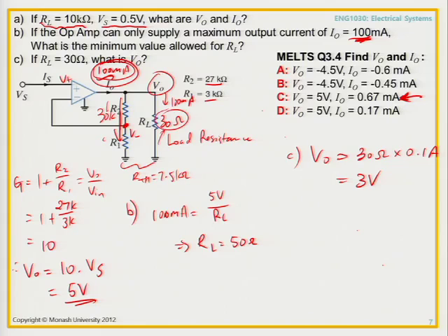And if we stick a 30 ohm resistor here, we're going to draw the maximum current out of the op amp, which will mean that V out can only ever reach 3 volts if we put this load resistor here. So you pick up a headphone and you plug it in. So this op amp is, say, the output amplifier for your audio.